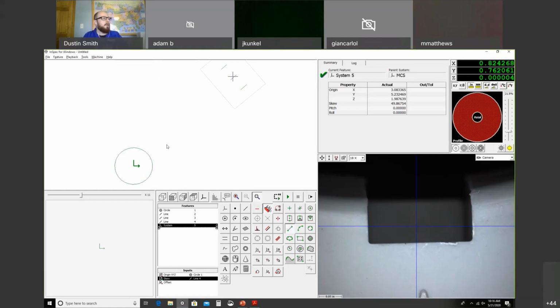Now when I go off and measure all the other dimensions on my part, it'll make more sense. If you're doing true position to any of the diameters on the part, it'll have the right X and Y locations. If you see a lot of parts like this, if you get a lot of prints asking for offset origin and you're having a difficult time with it, email training@atiquality.com and we'd love to follow up with you, give you some support, see what you're working with, and see ways that we can advance your skills in programming with those.